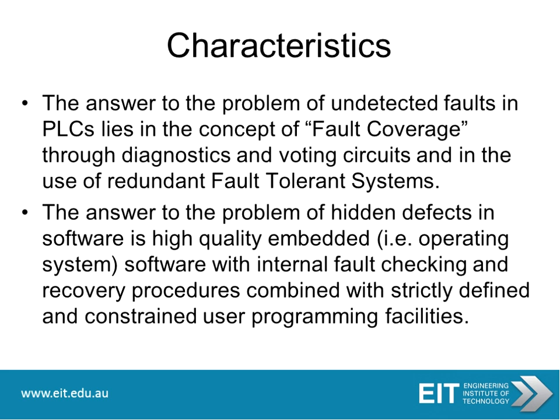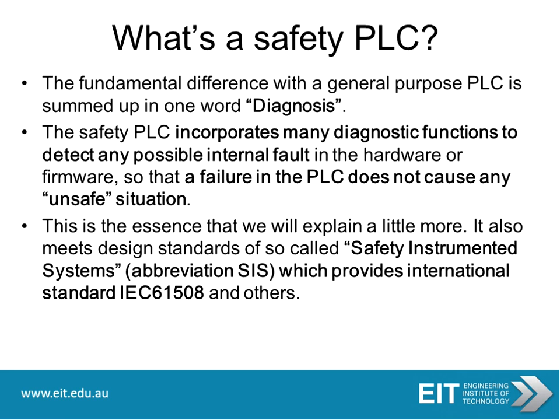Now getting to the characteristics of your safety PLCs. The answer to the problem of undetected faults in PLCs lies in the concept of fault coverage through diagnostics and voting circuits, and in the use of redundant fault tolerant systems. The answer to the problem of hidden defects in software is high quality embedded software with internal fault checking and recovery procedures, combined with strictly defined and constrained user programming facilities.